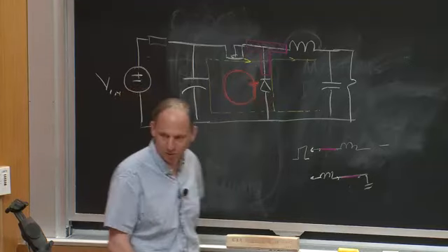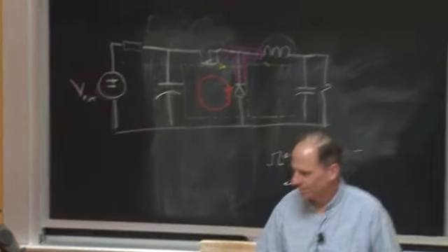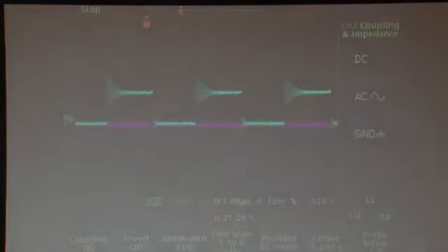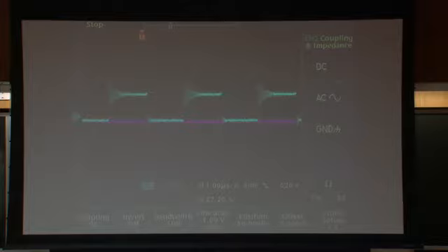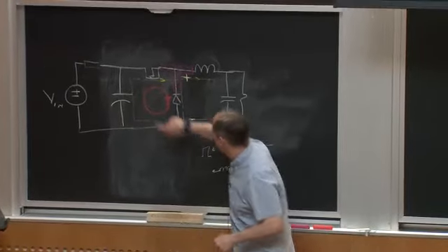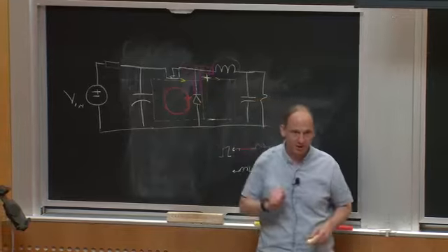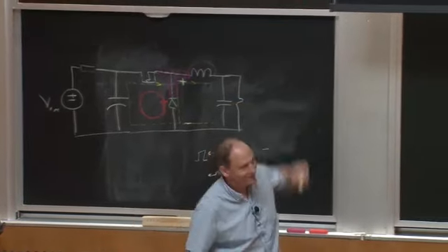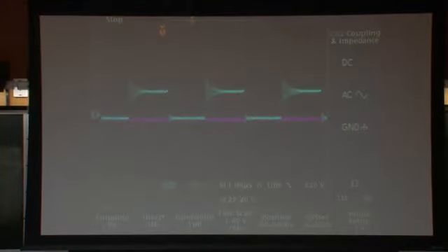Okay, so we can see the first one. And what you see is a whole pile of ringing in this circuit. What she's looking at is the voltage at the switching node. That's right. So it's this switching node voltage we're looking at, and there's all kinds of excess ringing there. Why? Because there's inductance in this loop which is ringing with things, and then it's settling down. That's pretty bad, because that can inject noise elsewhere in the circuit. It can even interfere with the circuit itself.